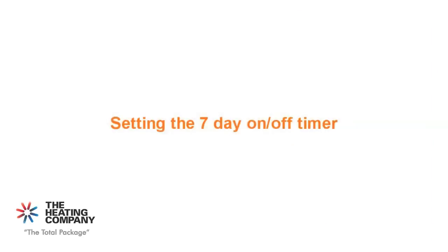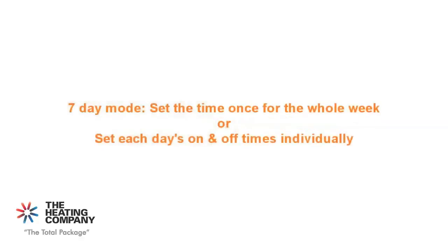Setting the 7-day on-off timer. This will allow us to use either 7-day mode, where we enter one day's times and those times will be applied across the whole week, or we can set each day's on and off times individually.